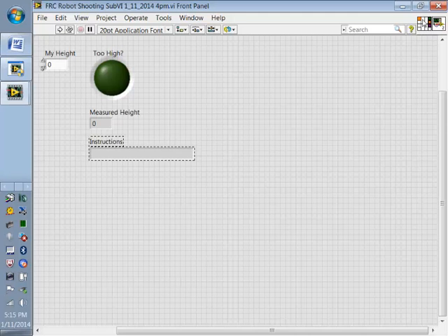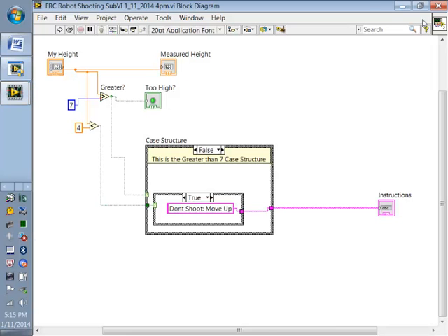So that would be a real drag if that were an actual limitation to LabVIEW, because maybe you've got a complicated algorithm that needs a lot of information. It turns out that one of the ways to solve this problem is to use a function to create a new data type that's very important in the robot code. The new data type is called a cluster.